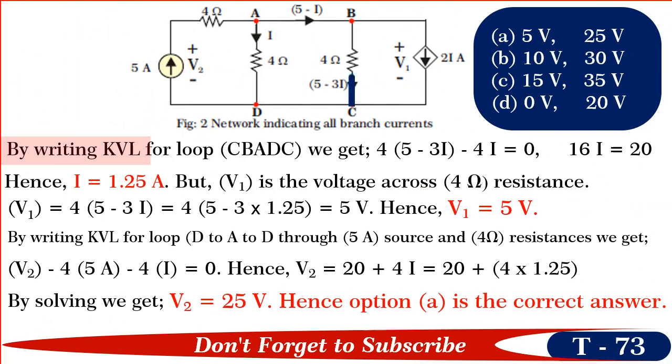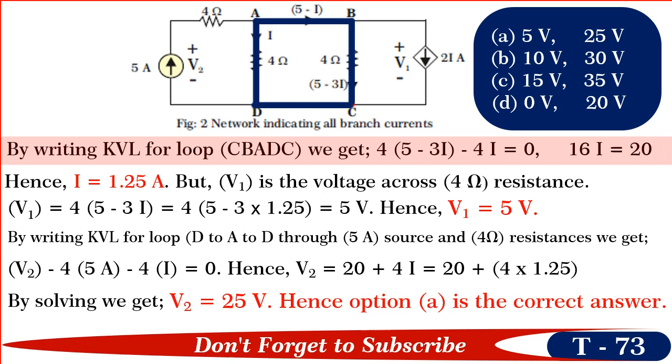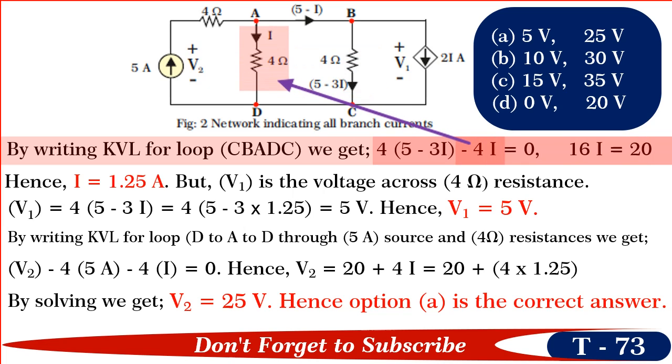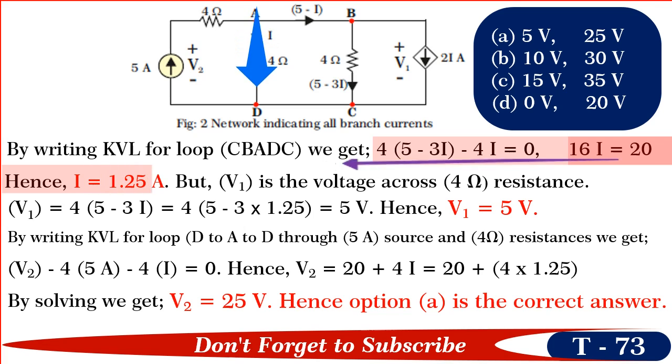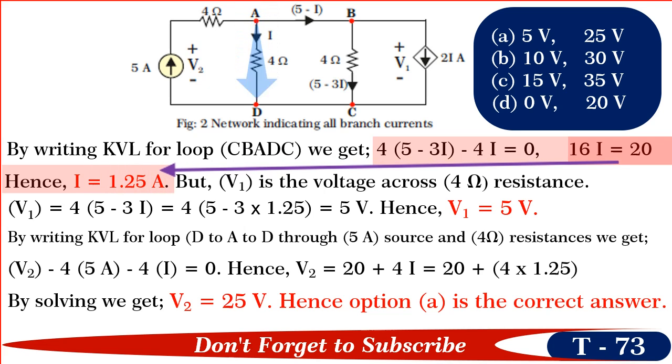So, by writing KVL for loop CBADC, we get 4 into 5 minus 3I minus 4I is equal to 0, from which we get 16I is equal to 20 and I is equal to 1.25 amperes.